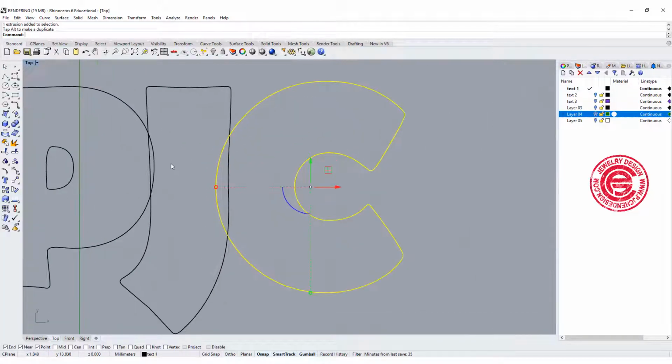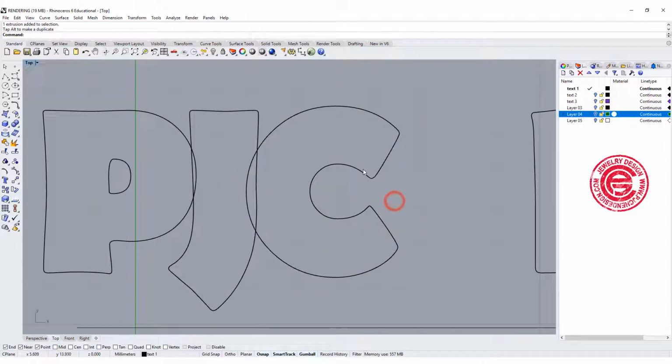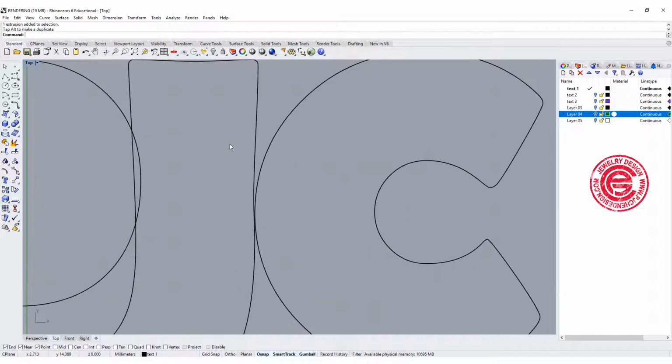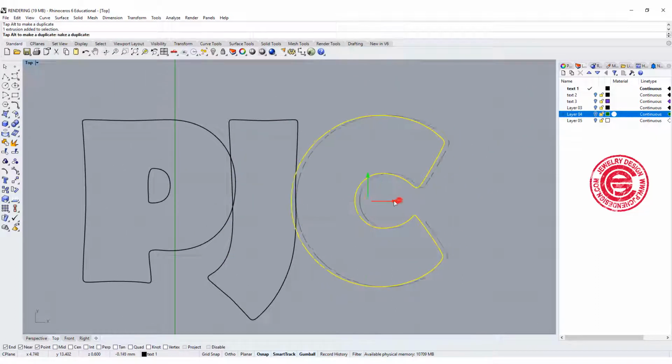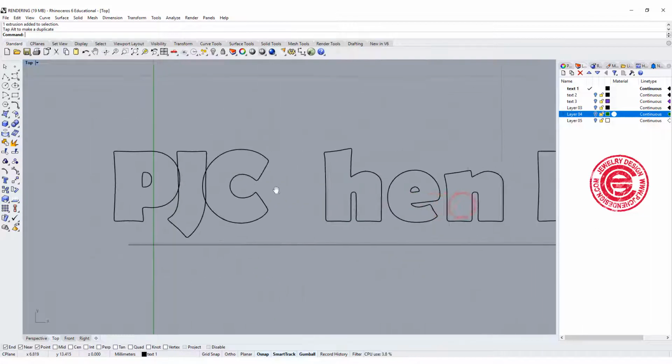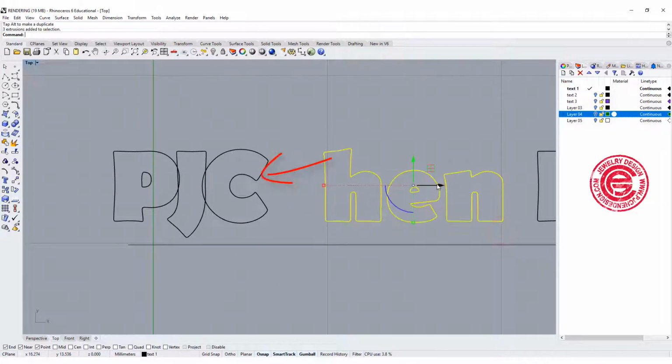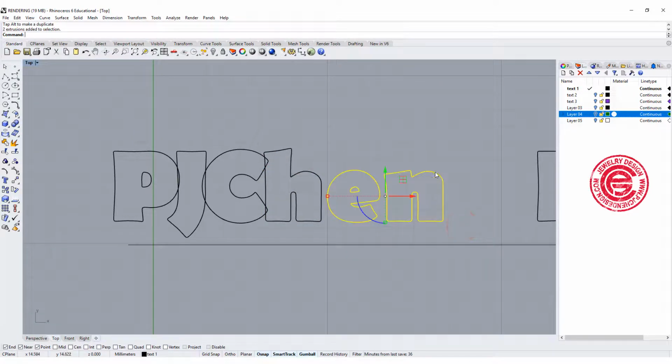Be careful on this. If your contact is too small, for example, you have this one just barely in contact, that's going to create a lot of casting issues. First of all, it's too sharp in this area, and you may have an investment breaking in there. And second, the metal won't flow through it. So make sure that they have very good contact, while at the same time it's still visible for reading. Now I'm going to move the text close to the center one by one.